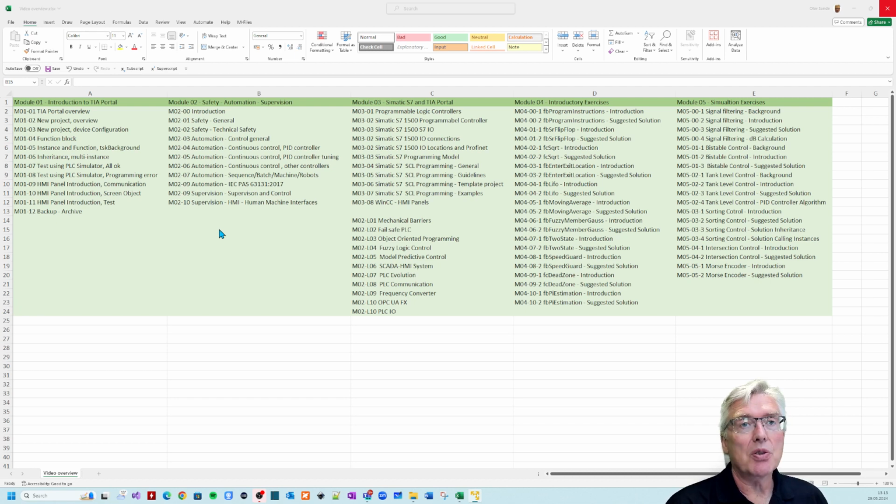You can do something without scripting, but it's time-consuming and tedious, and you have to make pretty much everything from scratch. There's a good thing with WinCC Unified: you have screen management and some built-in messaging system with alarms and so on, but it's just awful. So if you want to make some HMI system or SCADA, get hold of an external SCADA system and communicate with the PLC using OPC UA, for instance. So get a third-party product that's meant to be used as an HMI system.